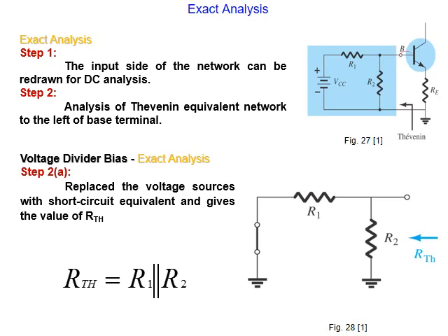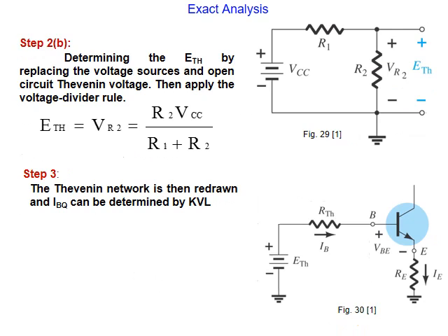But because here we have voltage drop VE, so with our voltage drop across RE in parallel with R2. Okay, now we need to use Thevenin to reduce the circuit. So what will happen, this supply will be shorted, and this resistance and this resistance, they are in parallel, and if we look from here for R Thevenin, they are in parallel, we get the equivalent.